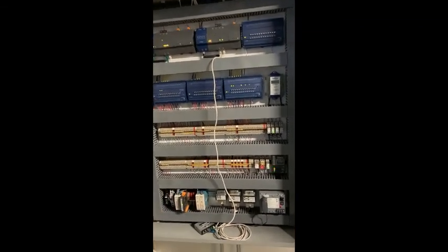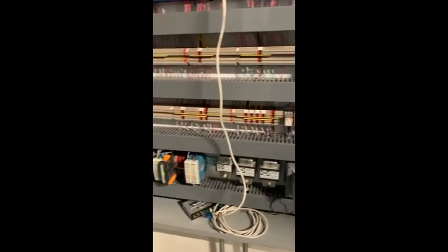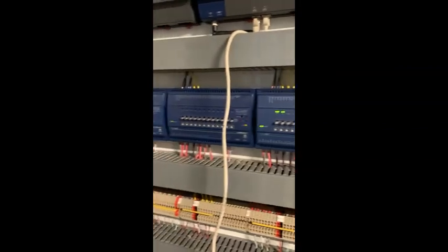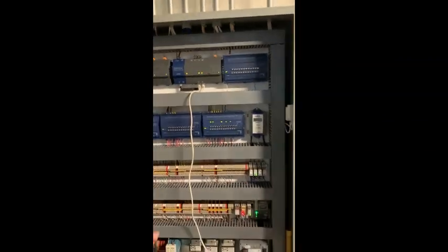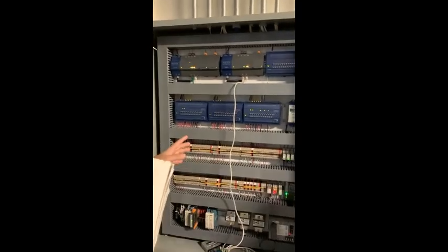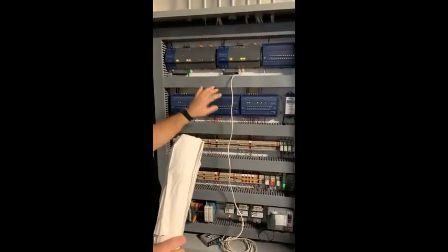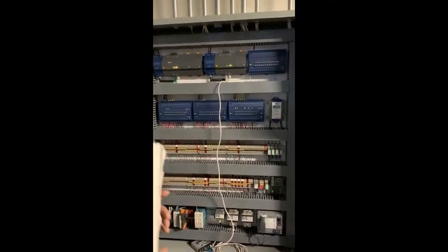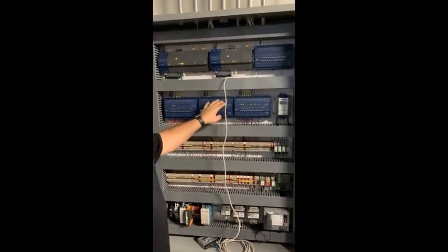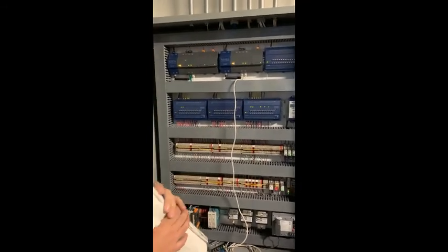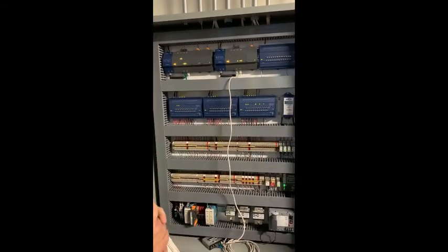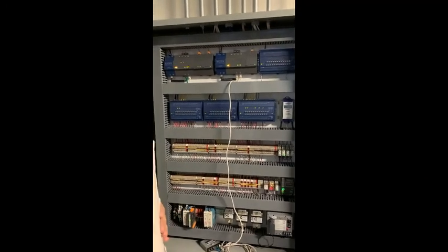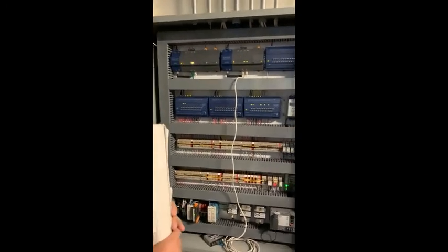2 to 10 volt DC. These outputs can be 0 to 10, or 2 to 10, or 0 to 5, or they can be 4 to 20. If you want to change an output, you actually have to pop this controller off. There's a jumper on the back. So they've already been preset, they've all been set for whatever. Anything that's not used would just be by default, I think, a 0 to 10 output. Yeah, you enable the 4 to 20 output.